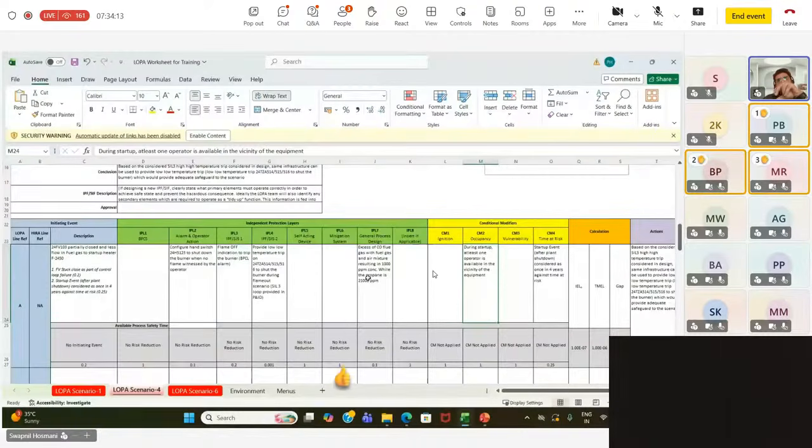So the quantum of fuel gas that is not able to sustain stoichiometric burning, and that will be passed on downstream, is considerably low because of the partial or constricted flow or partial no flow. Okay, so in that case, here I'm taking credit, because my volume of fuel gas is considerably low and it will never reach the mixture LEL concentrations. So that is why here I'm taking credit.